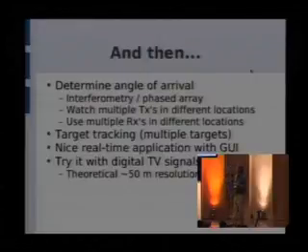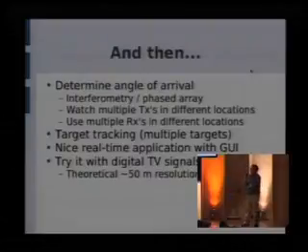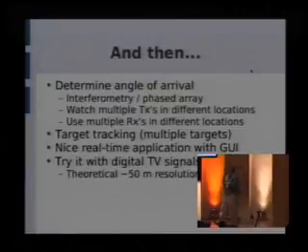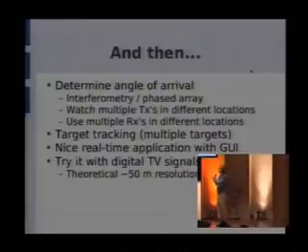And the trick is to figure out, what do I care about? So there's a bunch of different algorithms. People have been at this radar processing really for a long time. One of the ways it's pretty easy is if you just start by only looking at stuff that has a non-zero Doppler. The stuff that's not moving, probably I'm not interested in, since I know that the transmitter's not moving and the receiver's not moving. So we get rid of those.